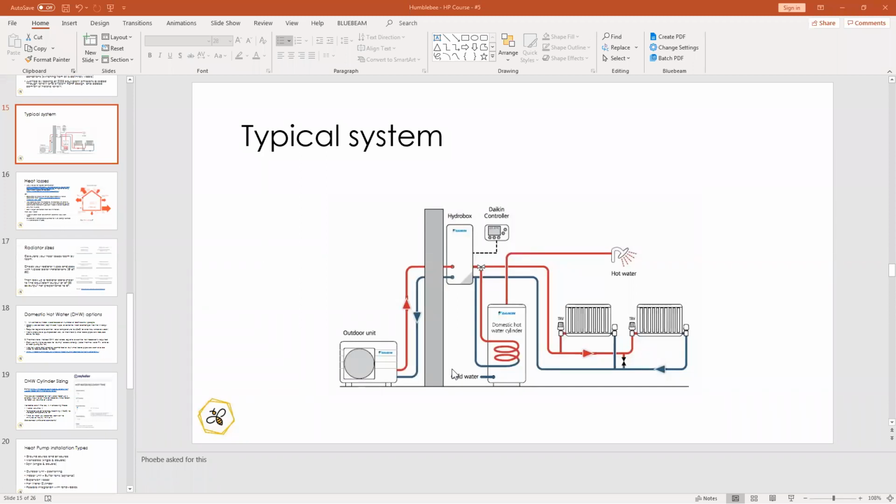I don't know your situation, but if you had a combi boiler, so you don't have an airing cupboard that we would normally say would hold a hot water tank. We've actually just completed something like that literally 2 weeks ago, and on the outside of the same wall where the combi boiler was, we built a little lean-to shed, effectively a very well insulated shed, and we put the hot water tank in there.